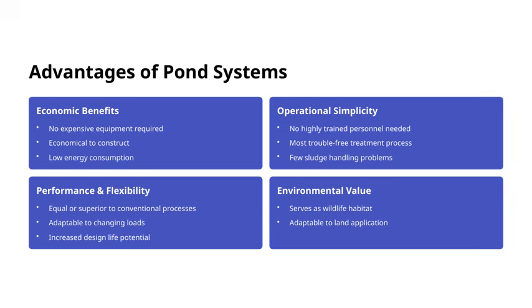First, from an economic standpoint, they require no expensive equipment, which helps keep costs down. They're also economical to construct and tend to have low energy consumption, making them a cost-effective choice overall. When it comes to operational simplicity, pond systems don't need highly trained personnel to run smoothly, and they are known for being quite trouble-free, with minimal issues related to sludge handling.